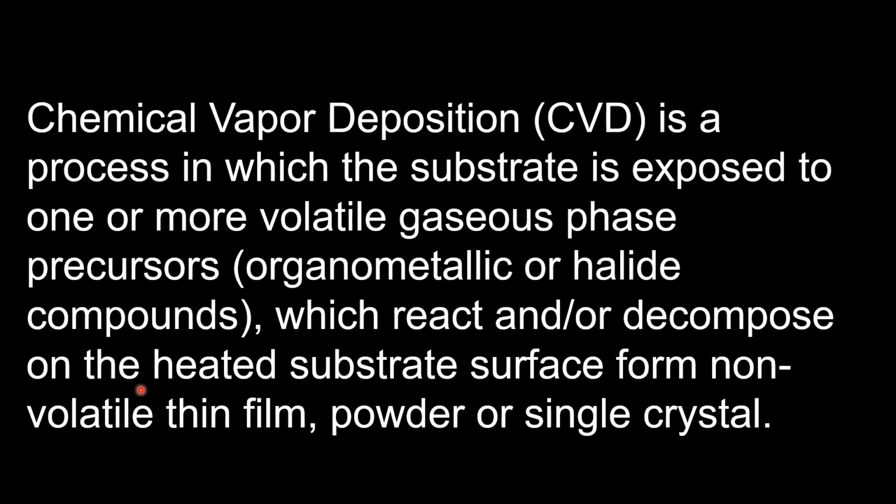and due to heat, the precursor materials chemically react with each other. They decompose due to heat, and then they get deposited onto the surface of a substrate as a thin film, or as a powder, or as a single crystal.